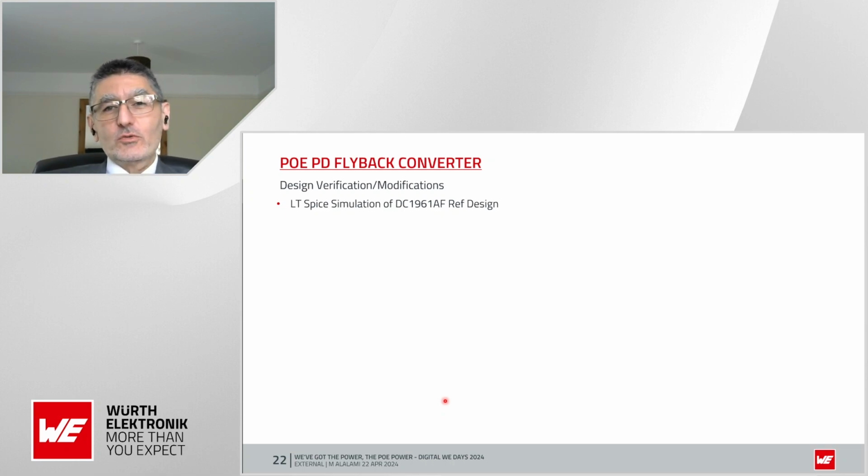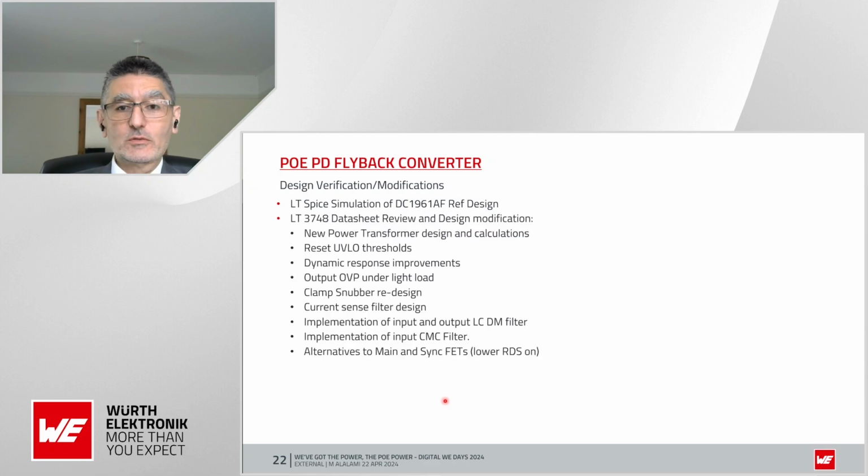So as a starting point, in order to verify the actual reference design and see what modifications we needed to do, we ran the LTspice simulation based on whatever was provided by LT for this particular module. And accordingly, I decided that naturally we needed a new transformer from an efficiency point of view. You will see why that is the case in a little bit. But we also needed to change the undervoltage lockout thresholds.